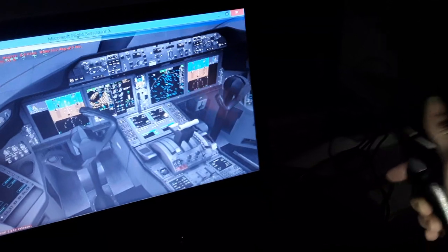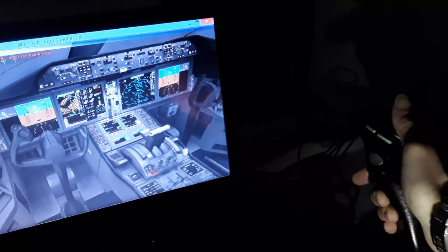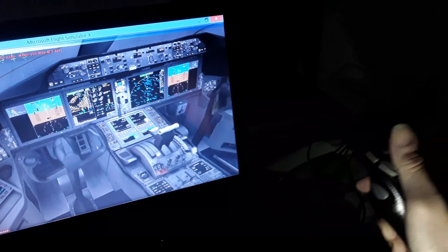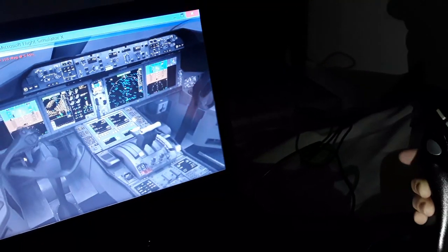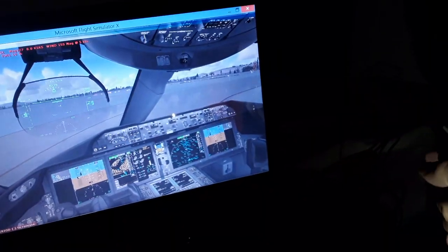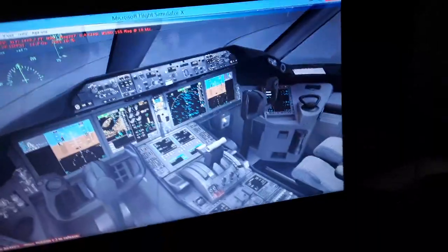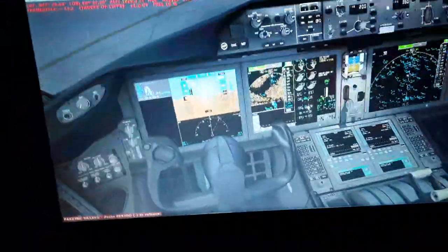So this is full flight controls over here. Our system uses the elevator for climb and descent, the pitch axis, the roll axis, the control wheel, making turns left and right, and the rudder pedals for the yawing axis. So you will see how we're gonna use all these things. So I will start maybe with the primary flight display over here.